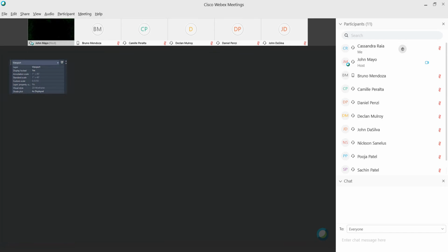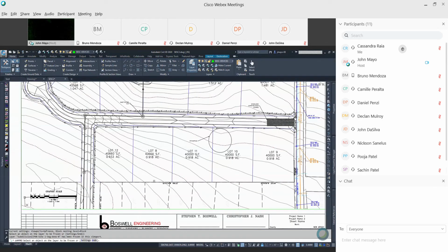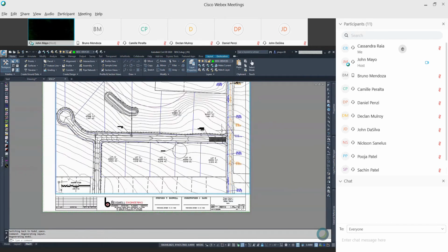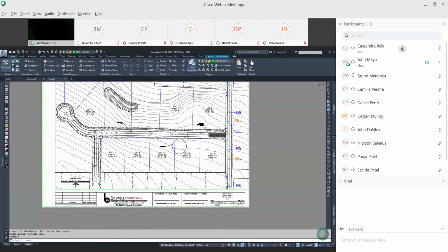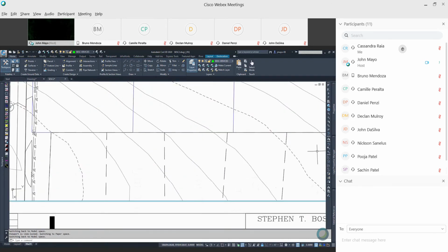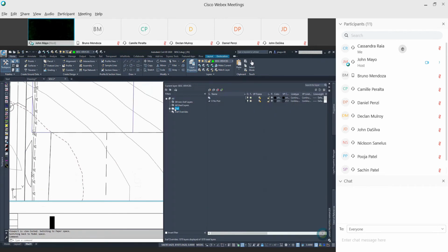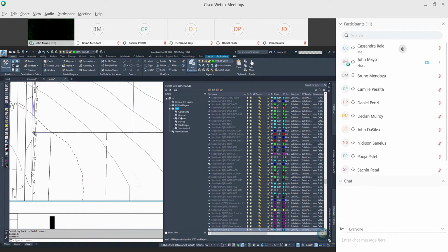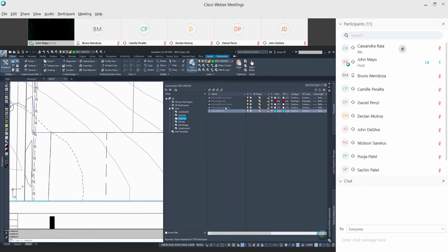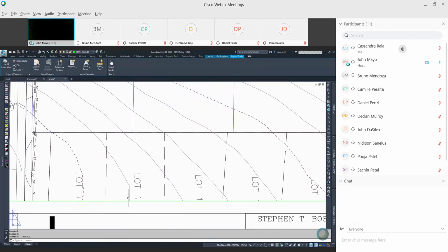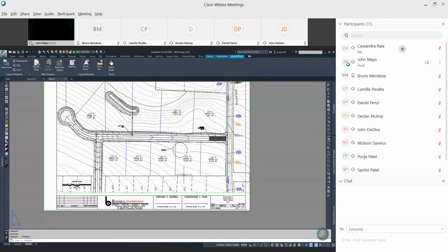And, you know, on my soil erosion sheet I probably don't need my metes and bounds, but I do have to add my road names and my lot numbers. They are there. I need to change their color because they're gray. So I would go into my layer manager. That's probably in the key map. And I look at this road name, parcel name. They are gray. Block name. Let's make them color red. Now they're printing a little darker. Right, and they've even got my street name.